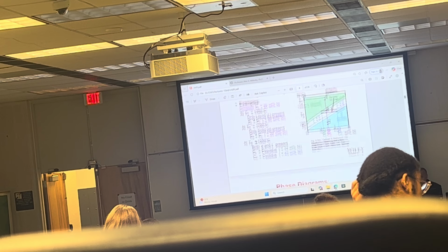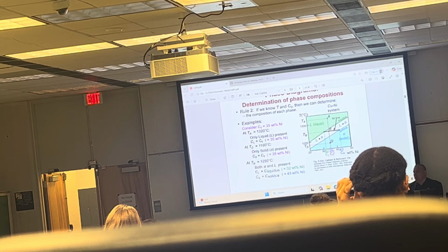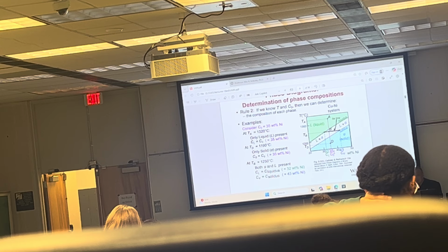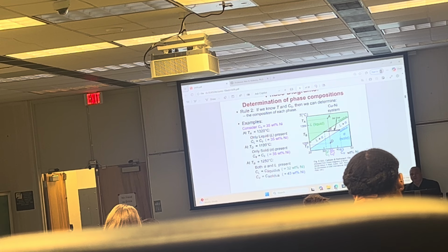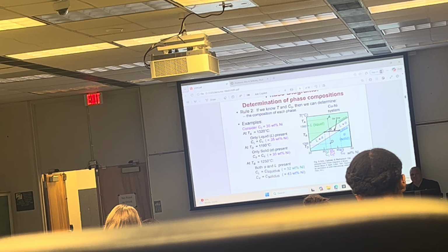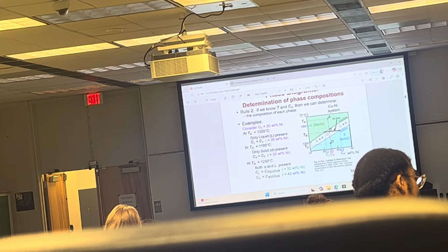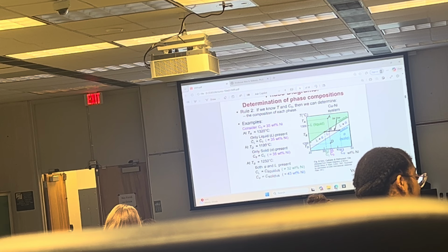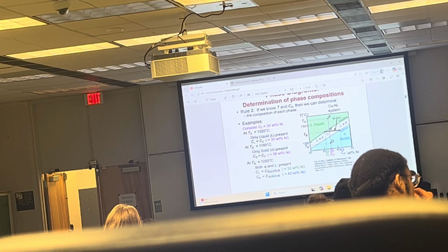If you go back here, then this is a different percentage. It does not have to add to 100 or whatever. Do you get that? Yes, sir. The composition only adds up when we add all three C's. What are the three C's? The C_L and the C alpha. No, nothing adds to 100 here. This is the composition of nickel in liquid and the composition of nickel in solid. This does not add up to 100%. That's what I'm trying to explain to you now.